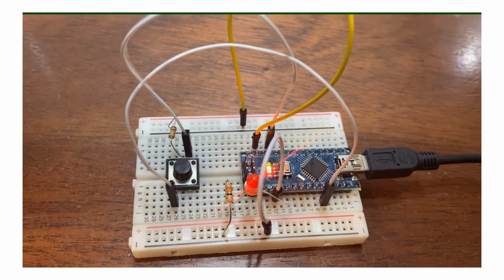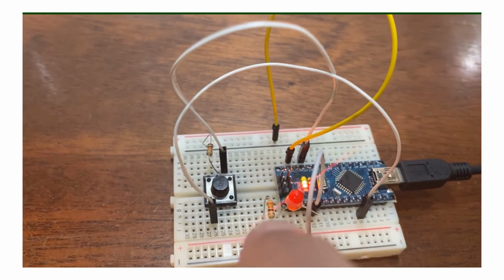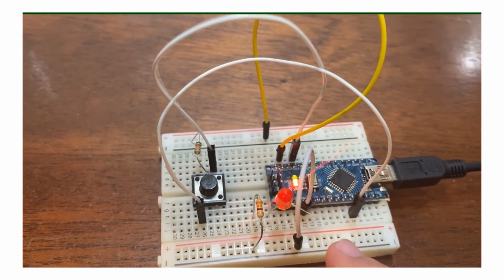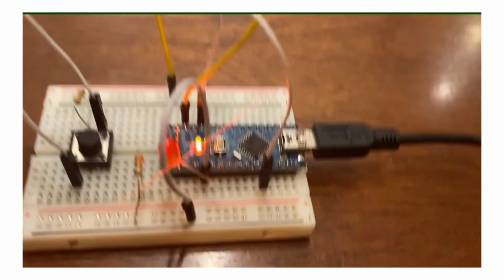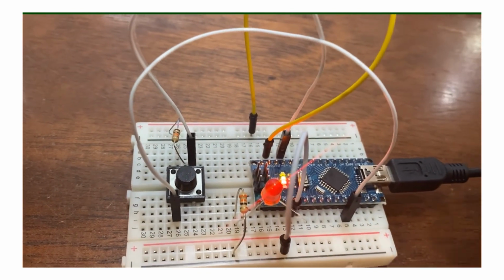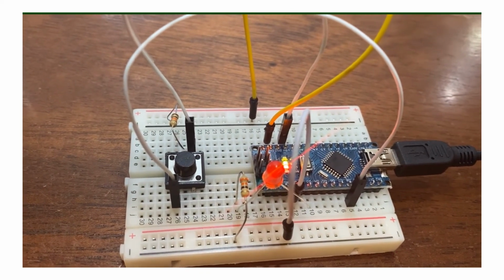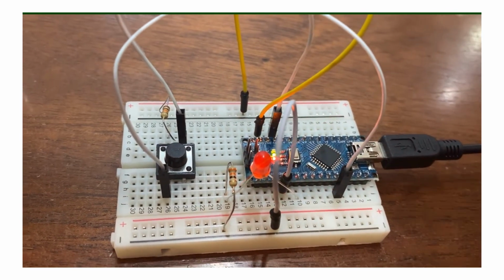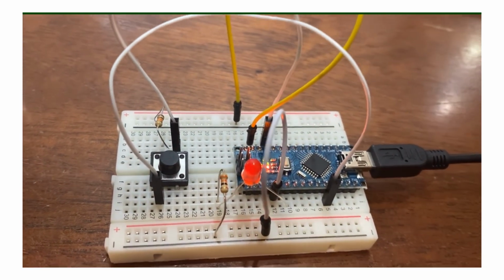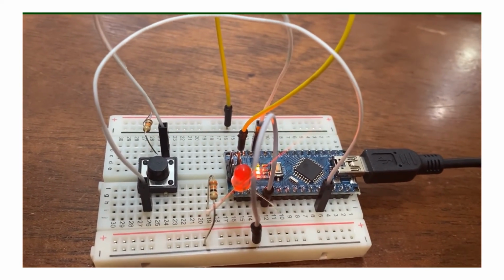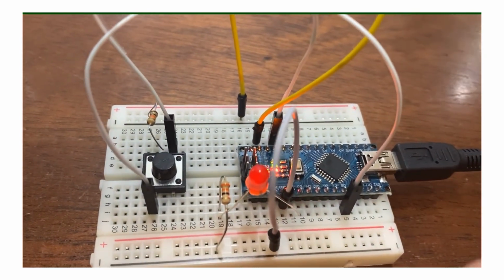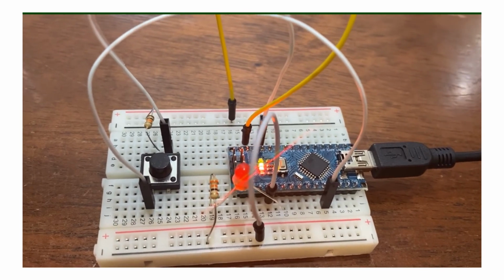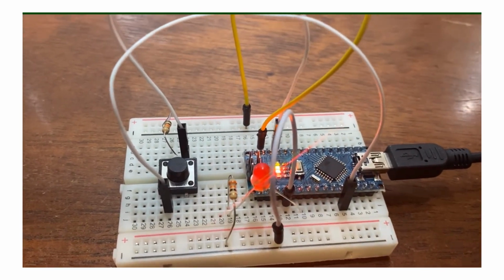Here is the Arduino Part 1B. It's a very similar circuit to Part 1A, except for the addition of the LED. The LED will be turned on or off according to the signal output that the button sends to the Arduino program. If the Arduino program receives a 0 from the push button, meaning that the circuit is not closed, the LED will not light up, but whenever you press down on it, the program will receive a 1 as its signal, which will tell the program to activate the specific pin for the LED, which in this case is 3. So whenever you press the button, the LED comes on. Whenever you release it, the LED turns off.